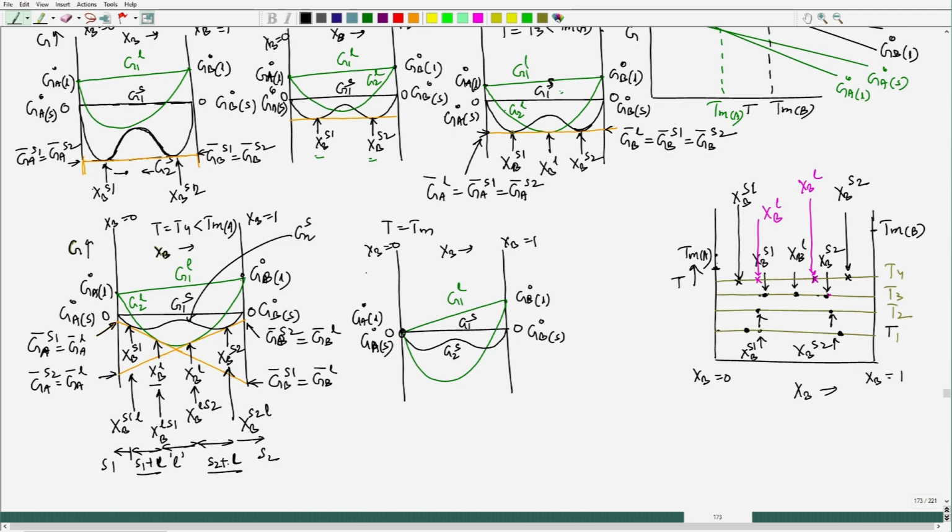So, now at this particular point we have solid and liquid pure A coexisting. Now, that can be taken as liquid line as well as solid line, fine, because here the free energies G2 of solid and G2 of liquid are merging. But on the right side we can still draw a common tangent. Okay. So, now we get one composition here, another composition here. So, this solid 2 composition is still drifting towards right.